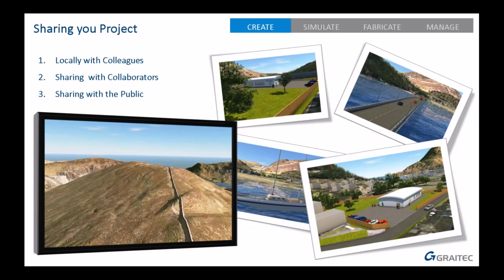Option 3 is if you've got BIM 360 Docs, there is a tool which links a civil surface to a Revit surface. So again, we can take the model out of Infraworks into Civil 3D, publish the surface to BIM 360, and then Revit can read that surface in BIM 360. Option 4 is we can output a CSV file from Civil 3D. So again, all these options require Civil 3D. Revit can read a CSV file.